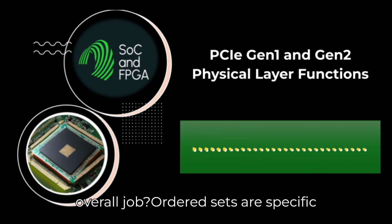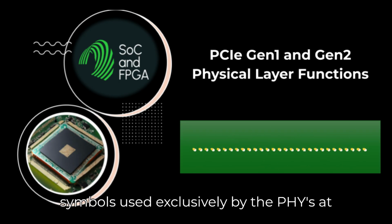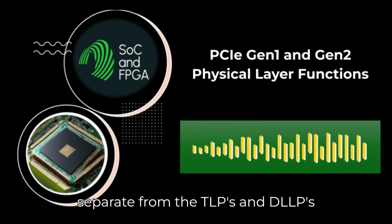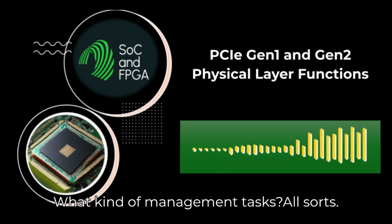Ordered sets are specific sequences of 10B symbols, mostly K symbols, used exclusively by the PHYs at each end of the link to talk to each other and manage the link state. They're separate from the TLPs and DLLPs carrying data and higher-level control. What kind of management tasks?